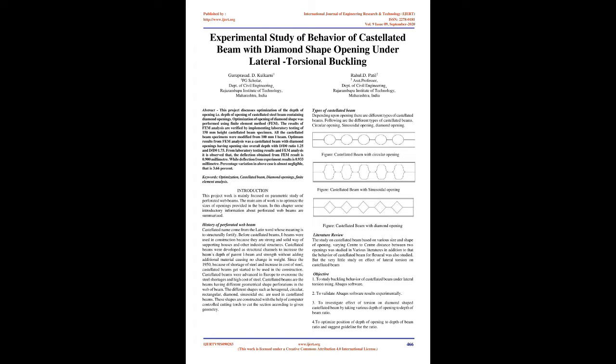The results of FEM analysis are verified by implementing laboratory testing of 150 mm height castellated beam specimen. All the castellated beam specimens were modified from 100 mm I-beam. Optimum results from FEM analysis was a castellated beam with diamond openings having opening size overall depth with D/D0 ratio 1.25 and D/D0 1.75. From laboratory testing results and FEM analysis it is observed that the deflection obtained from FEM result is 0.900 mm, while deflection from experiment results is 0.933 mm. Percentage variation in above case is almost negligible, that is 3.66%.